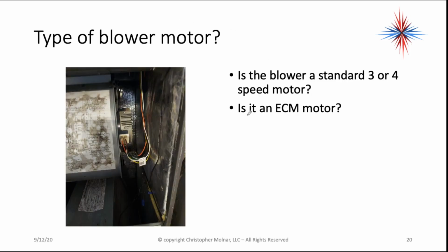What type is the blower motor? Is it an ECM blower motor, or does it have a capacitor, which has a typical 3 or 4 speed or single speed motor? Okay, again, look at the buildup and the signs of moisture on this label. You cannot say mold or anything because you don't know what it is. Mold can only be identified with laboratory tests.